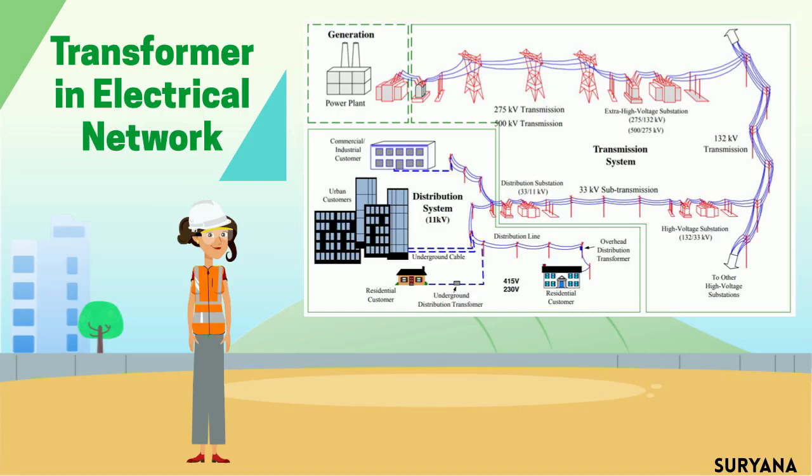Distribution feeder circuits usually consist of overhead and underground circuits in a mix of branching laterals from the station to the various customers. The circuit is designed by considering the required peak load, voltage, distance to customer, and other local conditions such as terrain, visual regulations, or customer requirements. In distribution, there are two types of system that have been used, that is, overhead lines and underground cables. High density urban areas are often connected in a complex underground distribution network, providing a highly redundant and reliable means of connecting to customers.